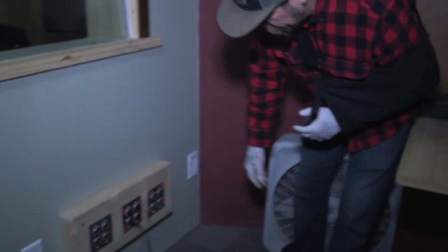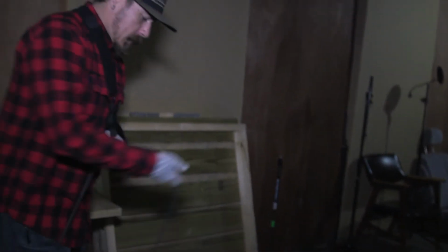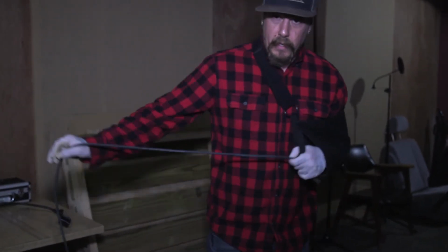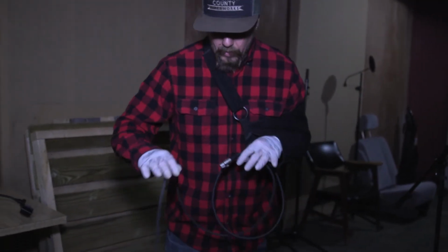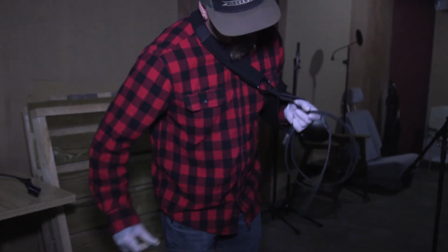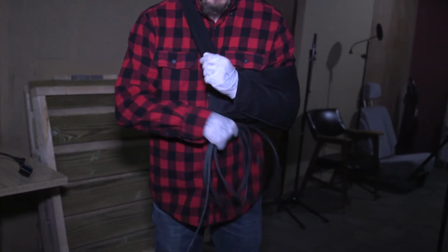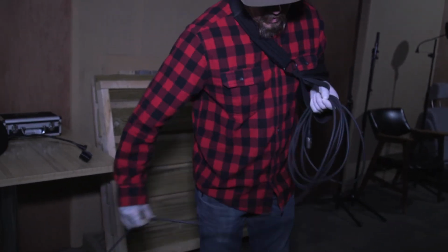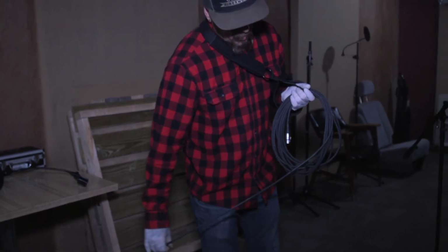Now I want to roll up these cables that I pulled out. So when you're rolling up cables, you don't want to strangle what I call strangle cables, where they're rolled up really tightly. You want them to be nice and loose, and cables usually have their own kind of natural way they want to be rolled up. So usually you can just kind of roll it up and twist and turn a little bit and feel where that loop should be made. It should just be nice and easy. Don't wrap it around your elbow and your shoulder, and don't wrap it around your hand real tight. The thing is, it should be nice and easy, nice and loose, so that the cable lasts a long time. Otherwise you start fraying the cords inside of it.